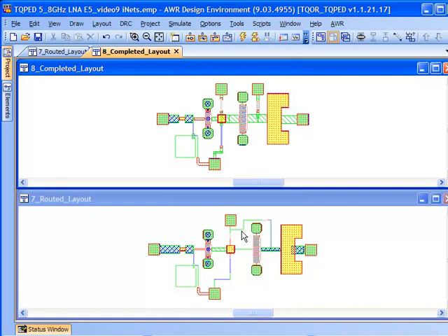Additionally, you will have noticed that I've gotten rid of that really ugly route that went around that bond pad. I'll have two VDD pads now, one for the second stage and one for the first stage, which probably isn't such a bad thing. It gives us a bit more isolation between the two. After we fabricate this chip, we'll have to look at some packaging effects, because there will be separate bond wires over there, and that may add some complexity to our consideration for stability. But in general, the design is roughly the same.